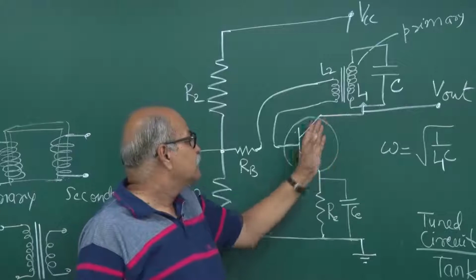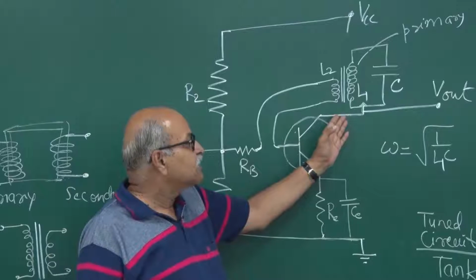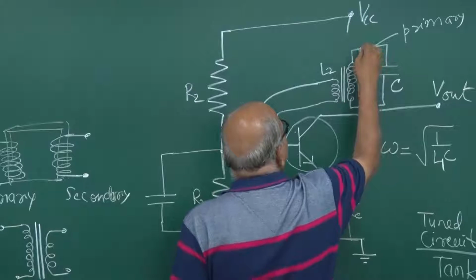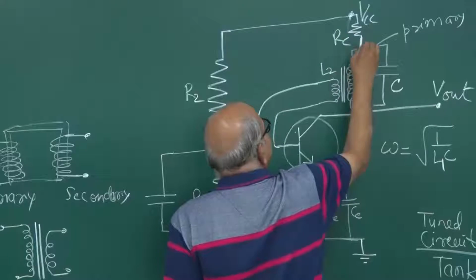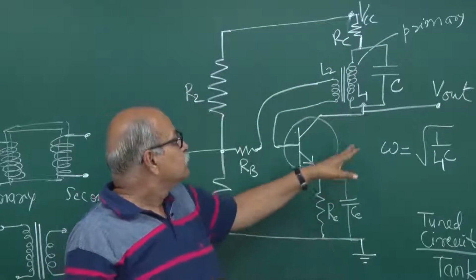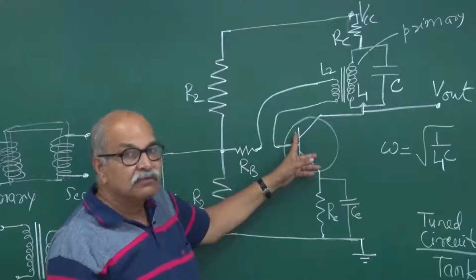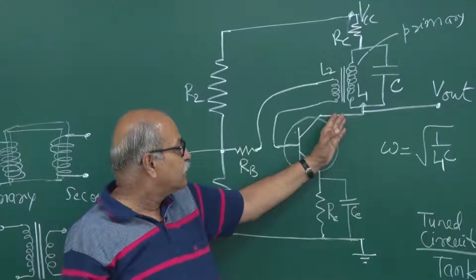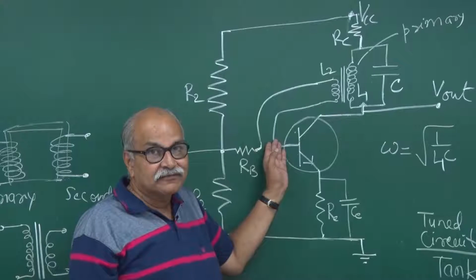you remember that in common emitter configuration, when this amplification takes place, then you have, by the way, I have not connected this thing to this circuit, you have to connect it here. So let us put a resistance and then connect it, so that this whole circuit is completed anyway. So in that common emitter mode, when you do amplification, the phase of the output signal and the input signal differ by pi, right?